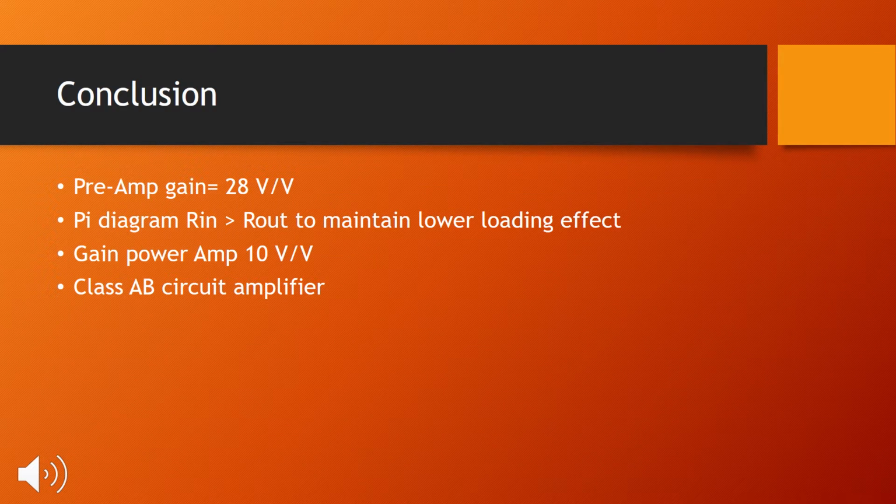The amplifier circuit we used is a class AB amplifier, since the goal of the circuit was to produce an output that shared similar characteristics as the input signal, but should have an amplified signal to fit the load requirement. Class AB amplifiers produce high efficiency and less distortion.